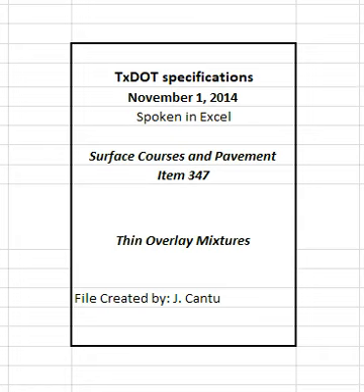4.4.2.1.12 Trial batch sampling. Obtain a representative sample of the trial batch and split it into 3 equal portions in accordance with TEX 222F. Label these portions as contractor, engineer, and referee. Deliver samples to the appropriate laboratory as directed.